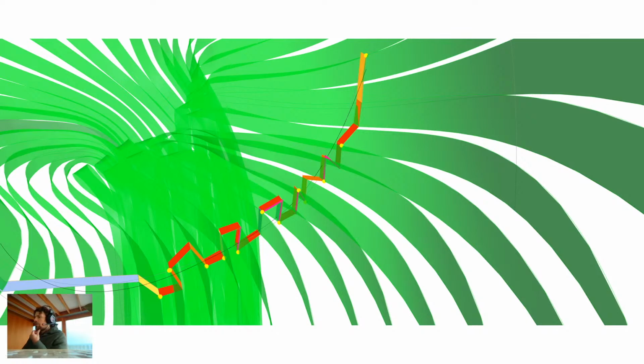Now the other thing that we used a hologram for, which we'll talk about in this workshop as well, is fabricating these steel brackets that fit through the structure. They're incredibly complex things. There's a whole lot of work that went into making them possible to build, but essentially the brackets need to join the timber boards together, and they need to be buildable. So you can't have very, very tight angles, or you wouldn't be able to bend them with a bender. You can't have very, very short bends, or they won't fit in the bender. They need to touch the surface of the board by a certain amount in order for it to work structurally, etc., etc.